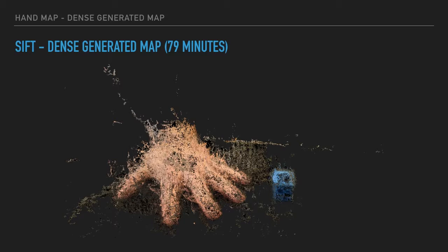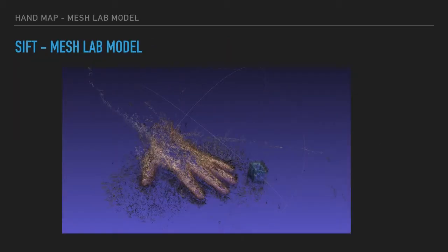I should note that the number of images that I input was far too big. Typically you would use maybe 30 to 50 images of a higher quality. That way you get the detail without needing to run so many iterations over the same images. Finally, I simply opened the output files in MeshLab and I had my 3D model of the hand and brick.